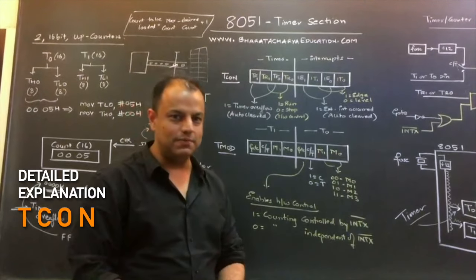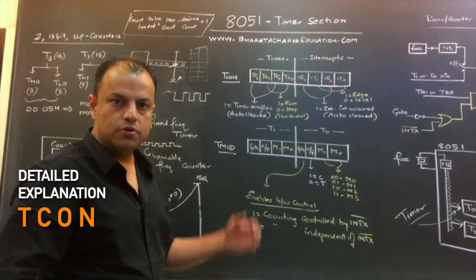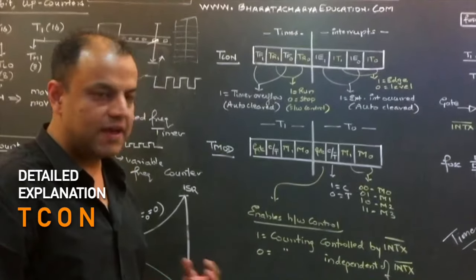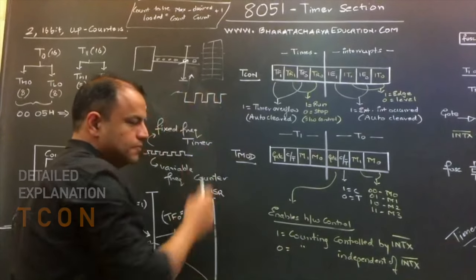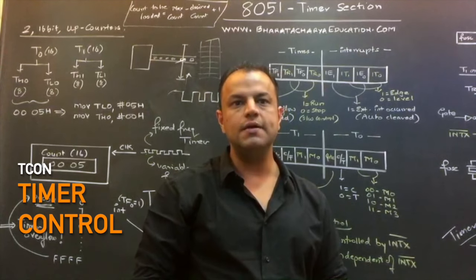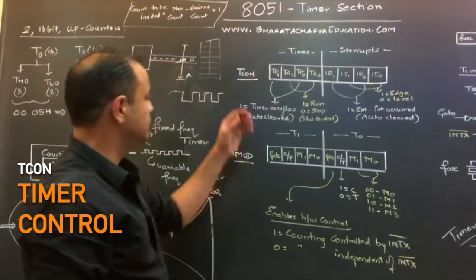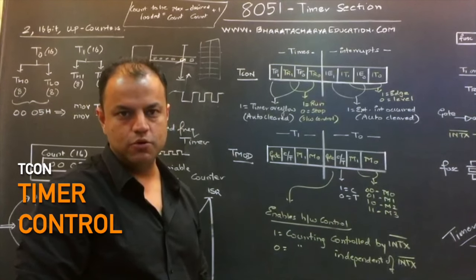A teacher who wants to quiz you on this chip would definitely want to know whether you know TCON and TMOD or not, because they have massive use throughout the chip. So, the first register, TCON. TCON stands for timer control. I repeat, timer control. Now, TCON is used to control the timer. TMOD stands for timer mode, from which you decide the mode of the timer.